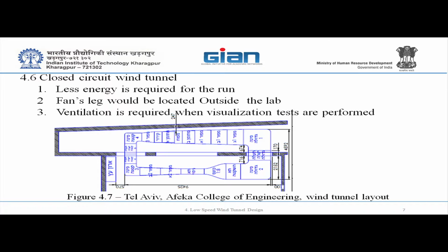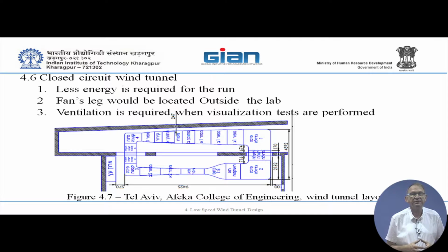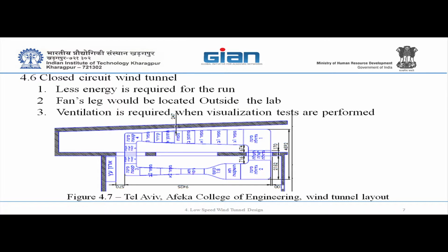The second factor is the expansion of the diffuser, the total angle of the diffusers. In closed circuit, you have two diffusers. One is out of the test section, and the second is from the fan down to the third corner before the settling chamber. We can go over the elements there if you like. Let me see there, I can see you and then.